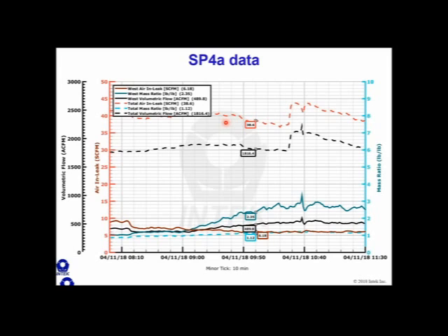case. Now, we already know that the customer said there's high air in-leakage, but what information can you glean from this plot? Not only is air in-leakage high, but why is it imbalanced? What are your guesses as to why the flow rates are different in the two lines? Go ahead and answer that into the question box.